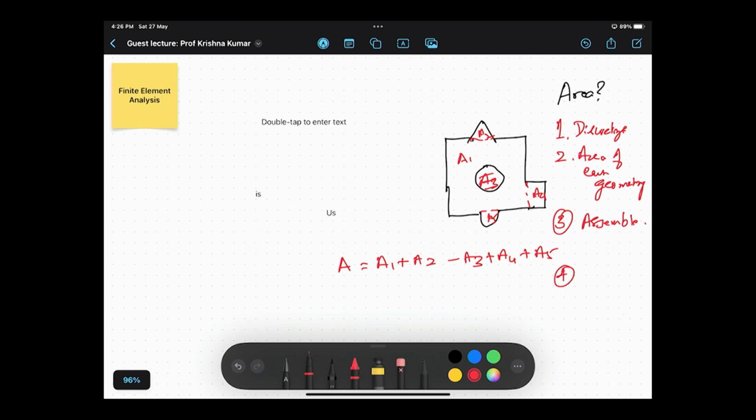The last step is, I'm going to solve. What is meant by solving? I'm just going to add and subtract as I see this equation, and I get the total area. So what essentially I have done is, I don't know how to solve this complete area, but I know that if I divide this into a number of geometries whose areas I know already, and I actually calculate that area, I'm not going to integrate. Actually, it comes out of integration and other things. I know it's pi r squared. I don't go into the derivations of it. I know its property. And then I put that in and sum them up. This is the essence of finite elements. There are finite elements. Here, the property of that element which we are looking for is what we call the area. The property which we will look for in some other place which we are going to see is stiffness and other things, which I'll come to in a minute.